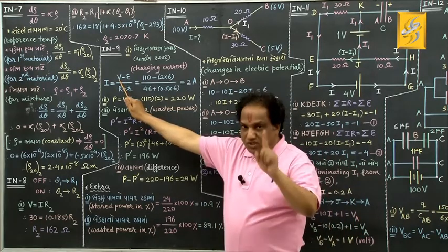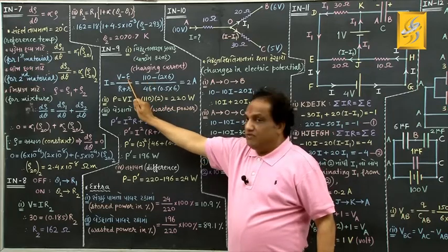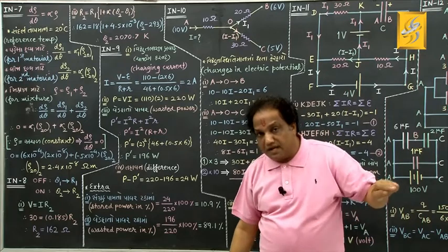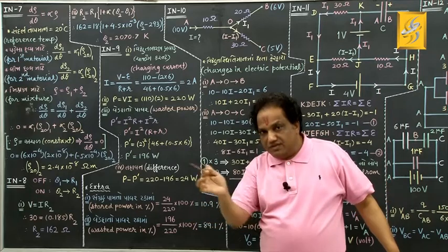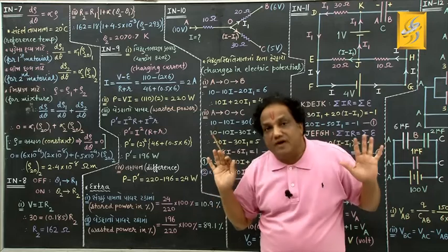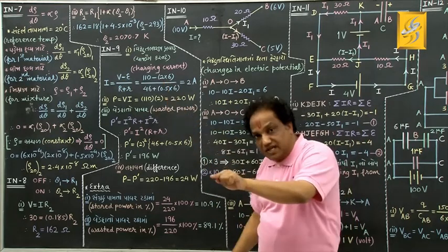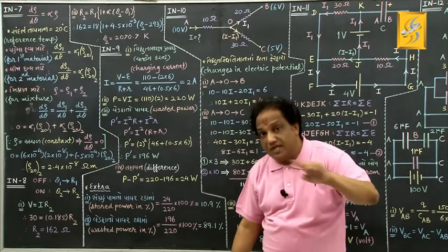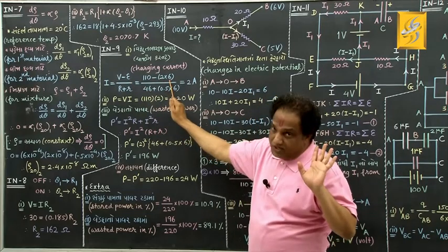This terminal voltage of the DC source, they have given 110 volt, minus as it is. This is the effective EMF. Now actually they have said to charge 6 lead storage cells connected in assisting connection in series. Come on, for an assisting connection in series manner, you know the resultant EMF will be the summation of individual EMFs, correct? And each individual EMF is, say, 2 volt, and such 6 cells are there in series in assisting connection. So 2 plus 2 plus 2, how many times? 6 times. That's why this effective EMF is 2 into 6, that is 12 volt. Got it?